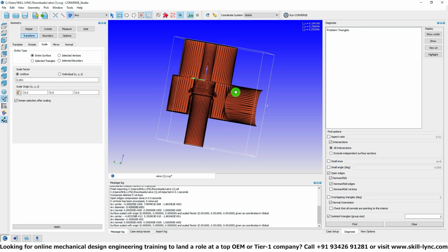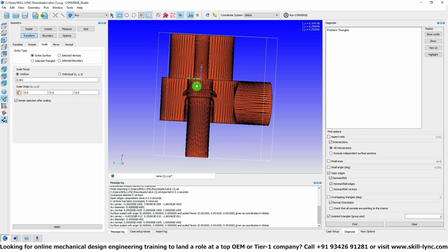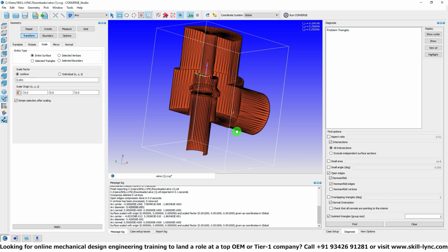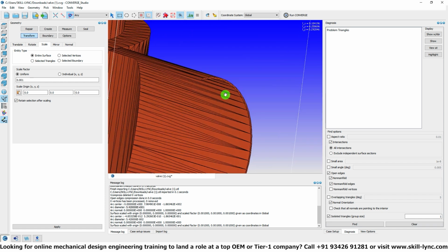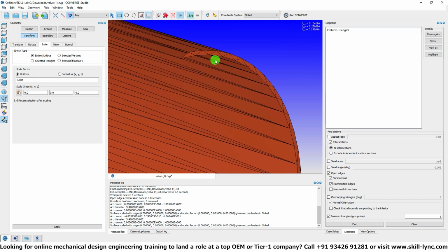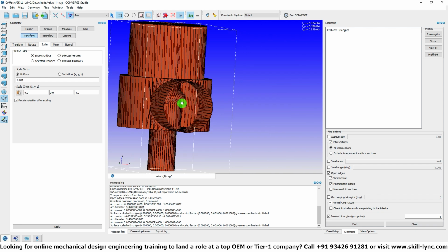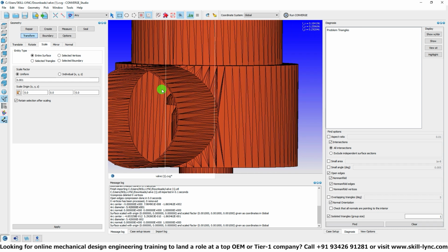So now if you look at this, you will basically see that this represents the cut section that we had looked at earlier, and you have to basically zoom in close to see that the solid components of the pipes have also been included, which is not required. So I'm going to hit redisplay, and my objective here is to make sure that I get only the fluid volume.